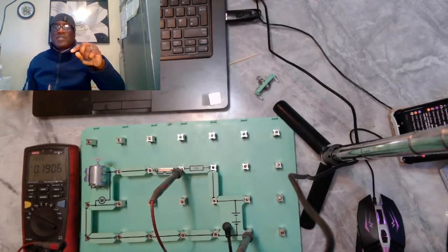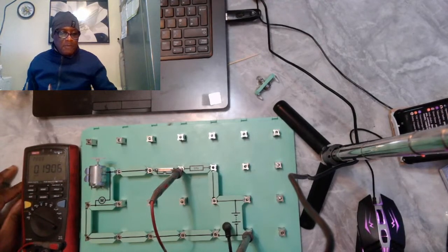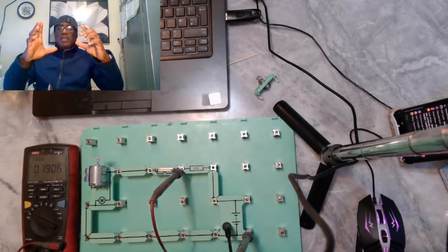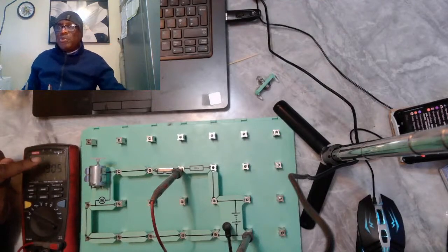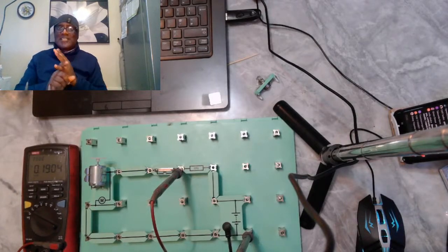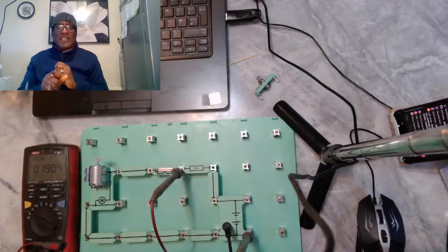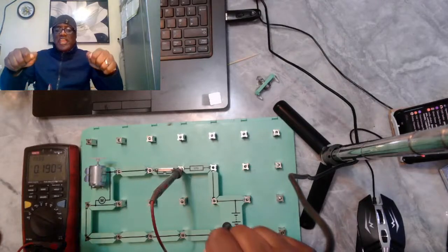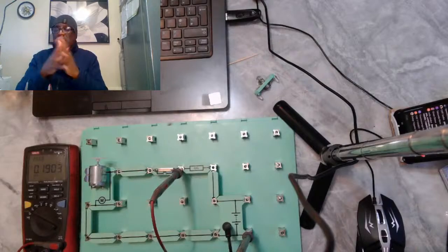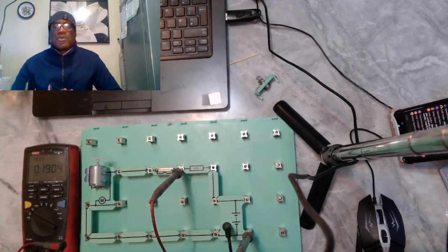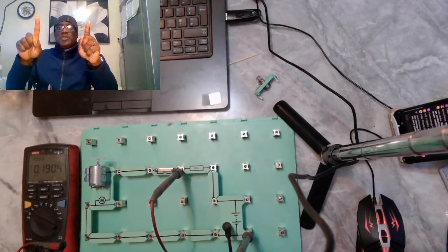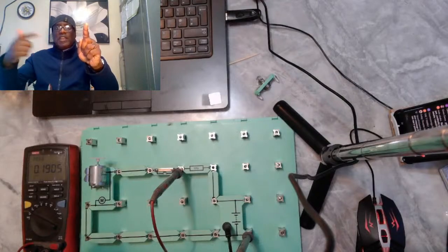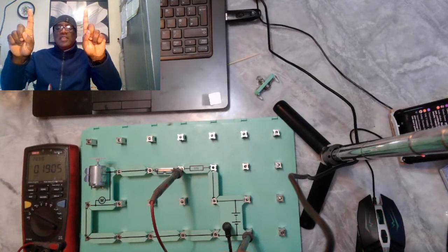I was thinking about checking for continuity there. When you check for continuity, sometimes you just find there's an open. You need to be able to read from your multimeter. Ladies and gentlemen, when you have an open, if you check your component for continuity, let's say you're checking an injector, a simple petrol injector, one wire from pin 1 to pin 2, just wound through a coil, right? And then it's the same wire.